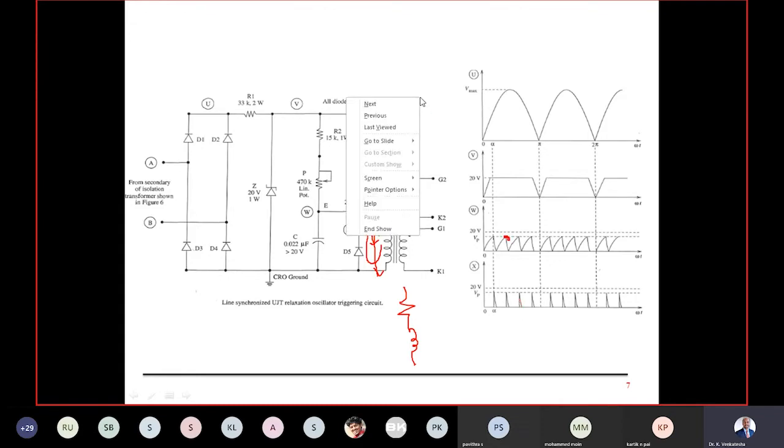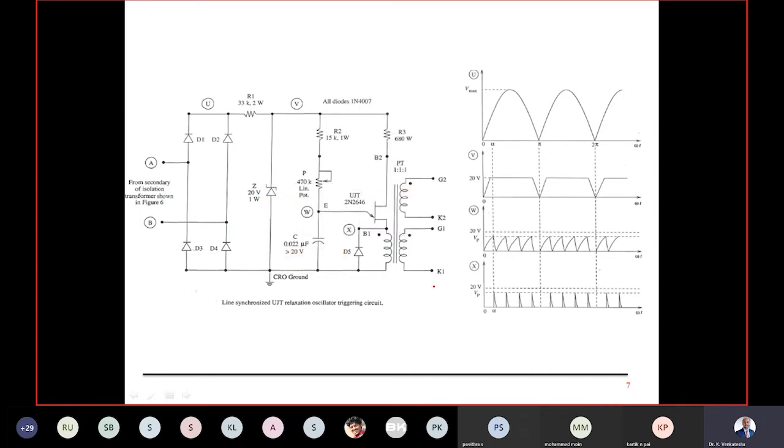So that is why we have the freewheeling diode across the coils, to ensure that your coil is reset when energy is not fed to it, which means that all the energy in the coil will be dissipated in the resistance of the coil itself. Again, it will come for the circuit part freshly to energize in a fresh manner. That's the basic idea here. The diode is for freewheeling, to reset my coil, to reset the energy of the coil.